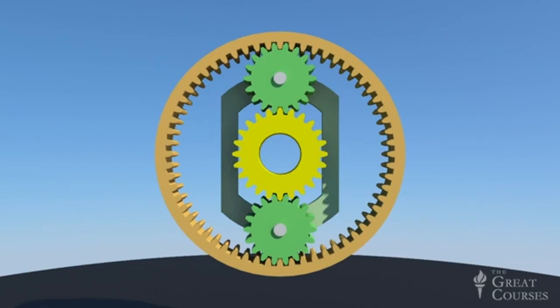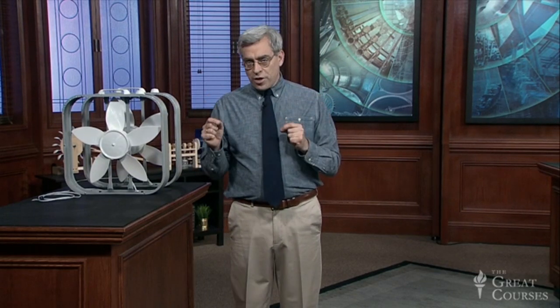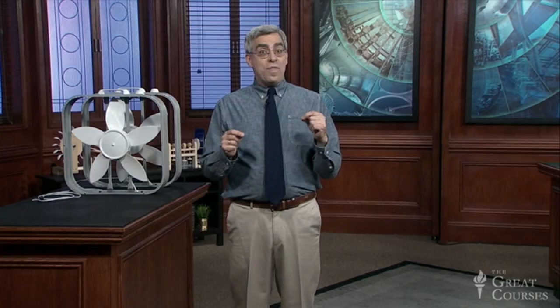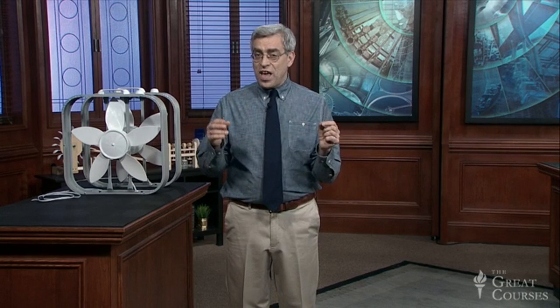The key feature of the planetary gear set is that all 6 possible configurations can be achieved simply by locking and unlocking components. Changes of configuration can be made instantaneously without the interruption of power input, and the gears remain in mesh continuously. Taking advantage of this very powerful feature, one type of 3-speed automatic transmission provides the 4 required gear ratios, 3 forward and 1 reverse, by linking 2 planetary gear sets together and then using a series of hydraulically operated clutches and brakes to lock and direct input power through different components of the 2 gear sets.